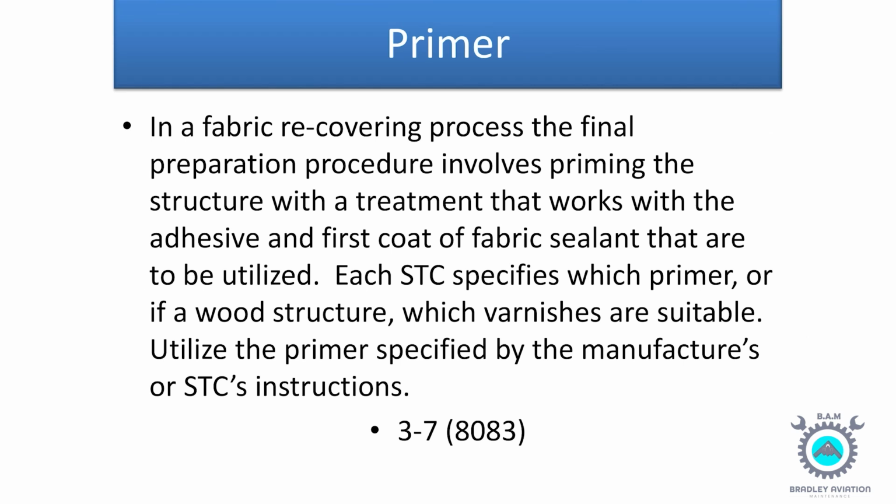In a fabric recovering process, the final preparation procedure involves priming the structure with a treatment that works with the adhesive and first coat of fabric sealant that are to be utilized. Each STC specifies which primer or, if a wood structure, which varnishes are suitable. Utilize the primer specified by the manufacturer's or STC's instructions.